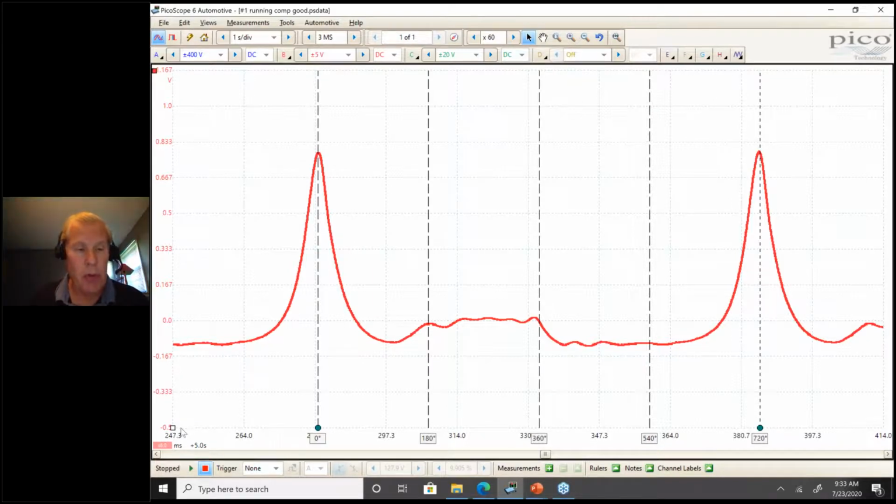So my cursors are over here. I want Pico to do most of the work for me. So I'm going to put this on bottom dead center. Now I'm pretty good with a mouse, so I got it pretty darn close, 179 point, oh, that's where it was, but it's not too far away. But with Pico, if I highlight that box and type in 180, the cursor will move automatically. So 180, watch the cursor when I press enter, and it moves right there.